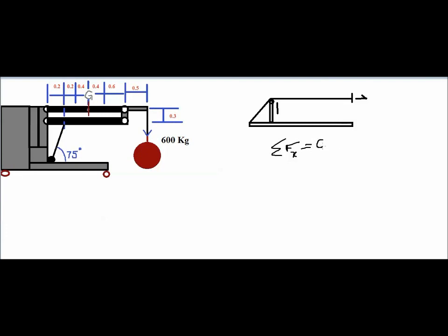is equal to 0. When you apply this particular formula, I always tended to include these forces also, but these are internal forces generated because of these forces. So it's not a new force. It is an internal force. The only external force acting is, maybe in the question it would have been given that there's a weight acting downwards, so that's the external force. The other external force is the reaction which is supporting the whole structure, which is this. And then there are a number of internal forces acting here.